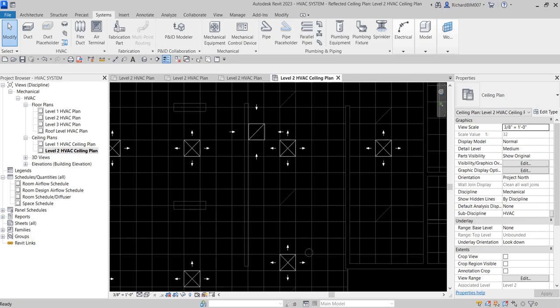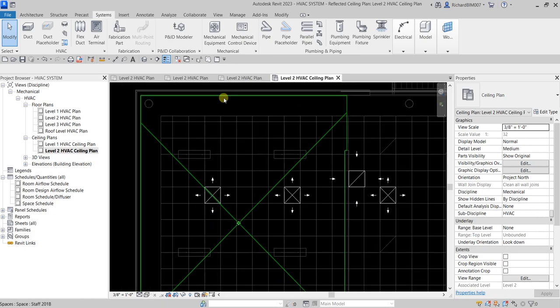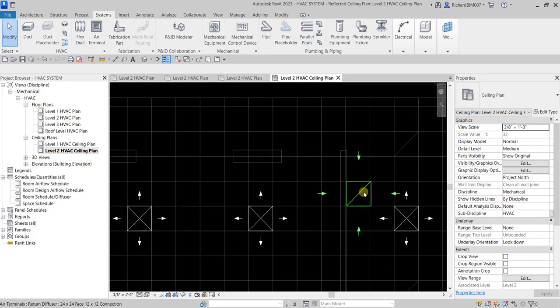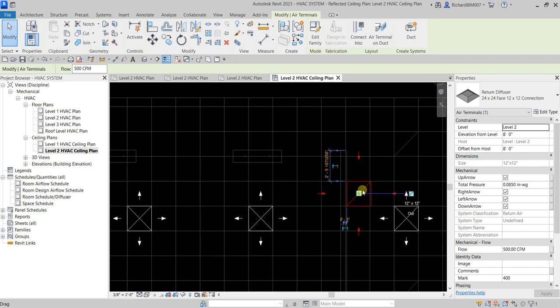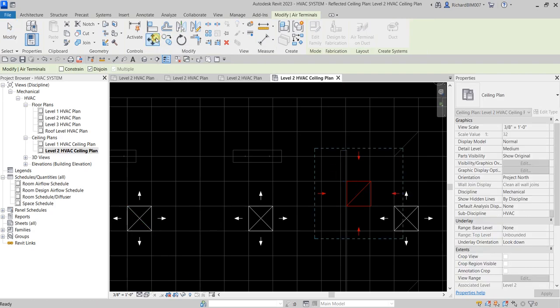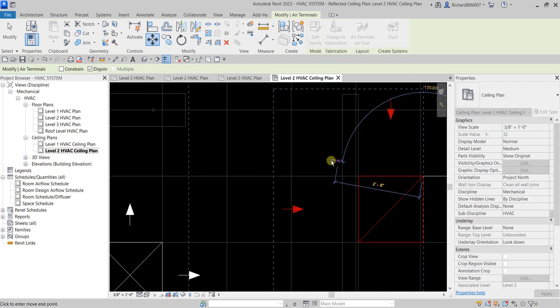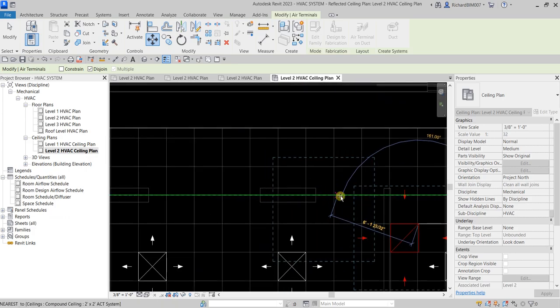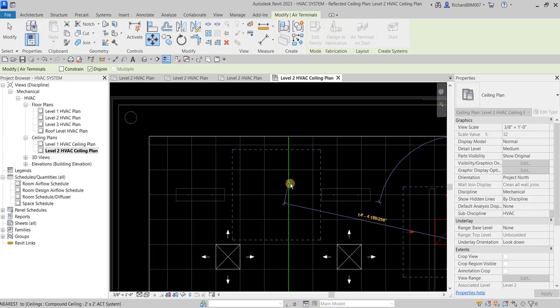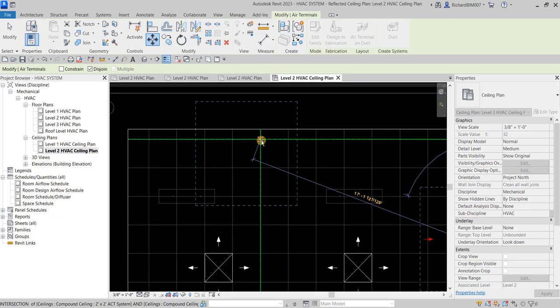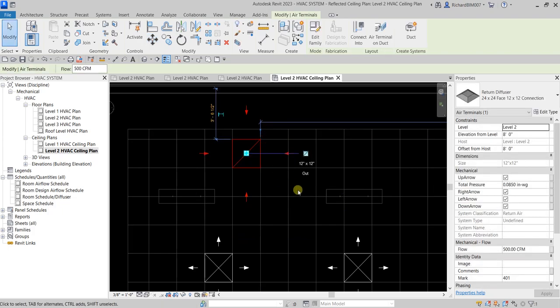After that, we're going to copy that. Let's align it first, so I'm going to just use Move. Select the object, and then select the Move tool. Then click the base point here, this one, and place it here at the top. Let's say somewhere here. Place one. There you go.